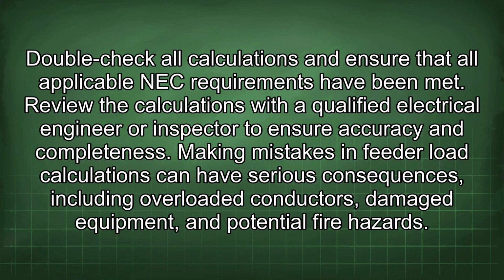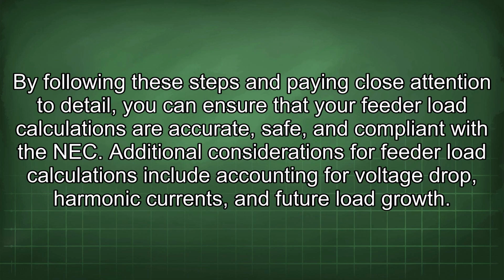Double-check all calculations and ensure that all applicable NEC requirements have been met. Review the calculations with a qualified electrical engineer or inspector to ensure accuracy and completeness. Making mistakes in feeder load calculations can have serious consequences, including overloaded conductors, damaged equipment, and potential fire hazards. By following these steps and paying close attention to detail, you can ensure that your feeder load calculations are accurate, safe, and compliant with the NEC.